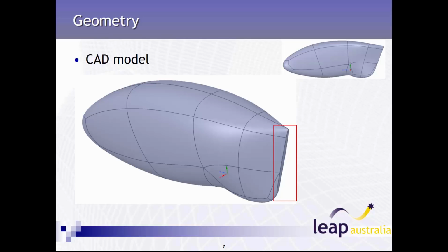Geometry can sometimes have issues when transferring from different file formats, so try and keep to Parasolid if possible. In the geometry process, watertight bodies are required. If there are any missing faces, small edges, or gaps between surfaces, it will make meshing an issue.